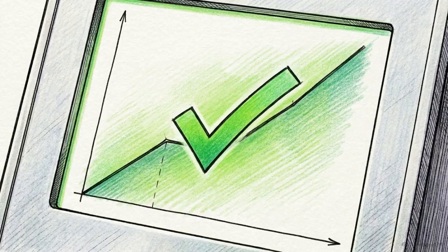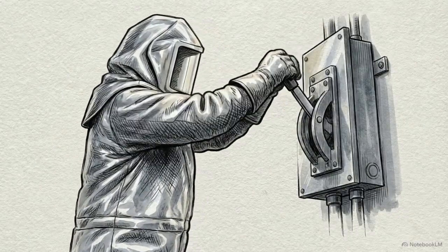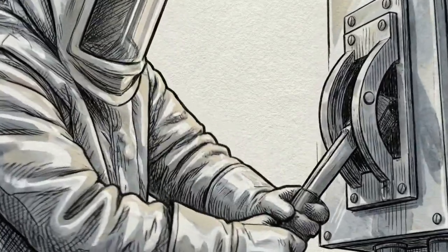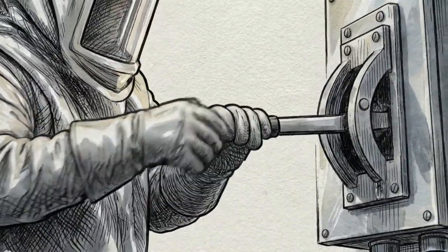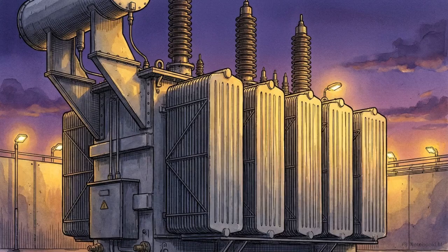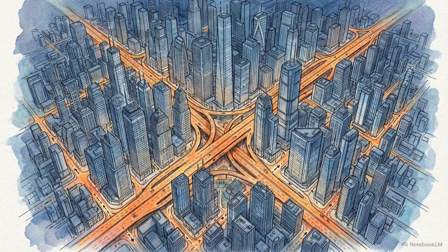The final physical test is primary injection. Massive currents are pushed directly through the high-voltage bushings to verify the external current transformer polarities and physical wiring match the relay's internal software matrix. The protection scheme is designed to clear internal faults while maintaining the asset's uptime during external grid disturbances. Transformer protection combines mathematical theory, adaptive algorithms, and physical fail-safes to secure the massive inductive components that sustain grid stability.